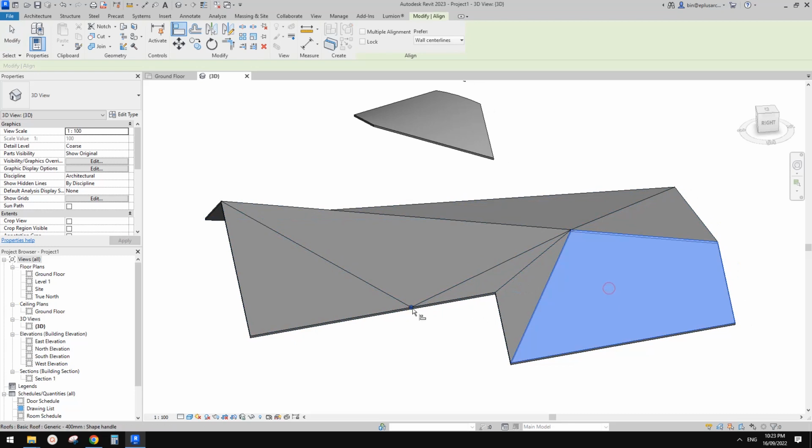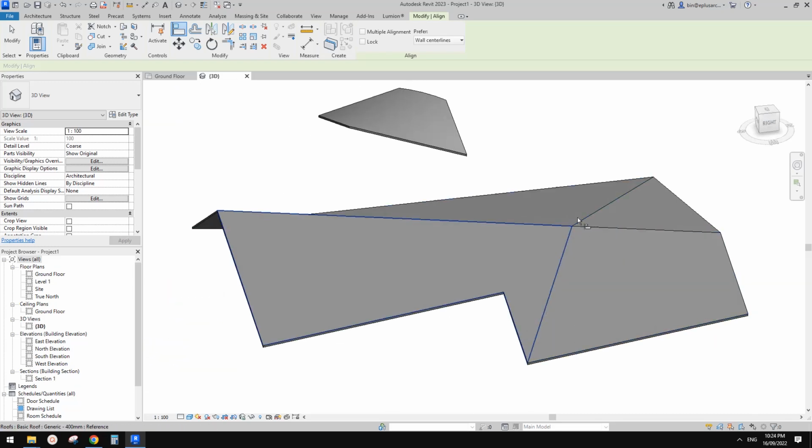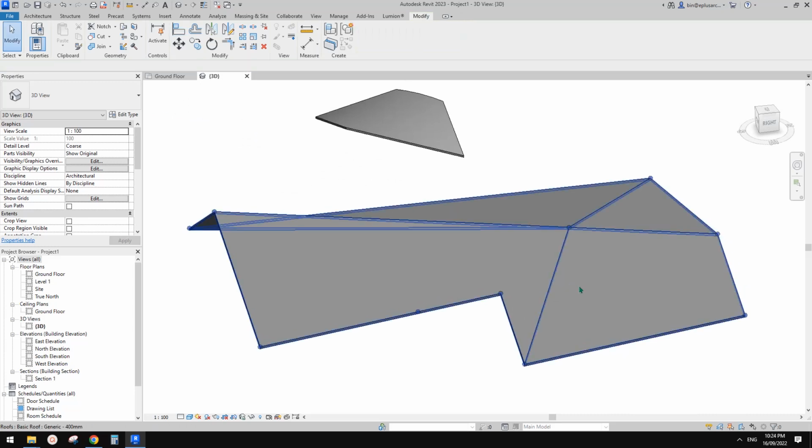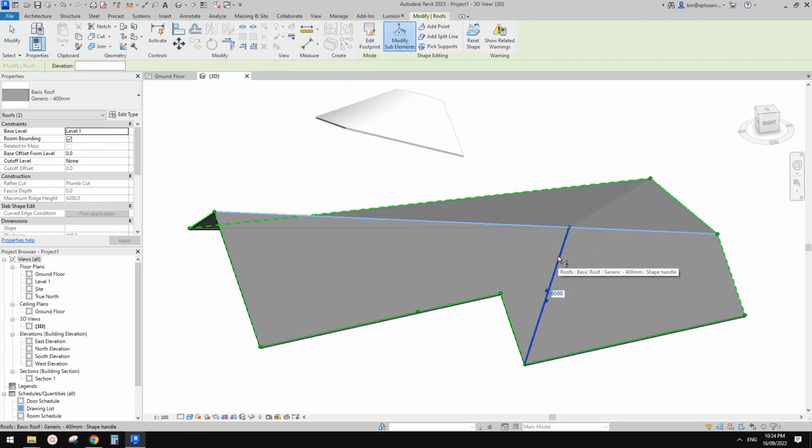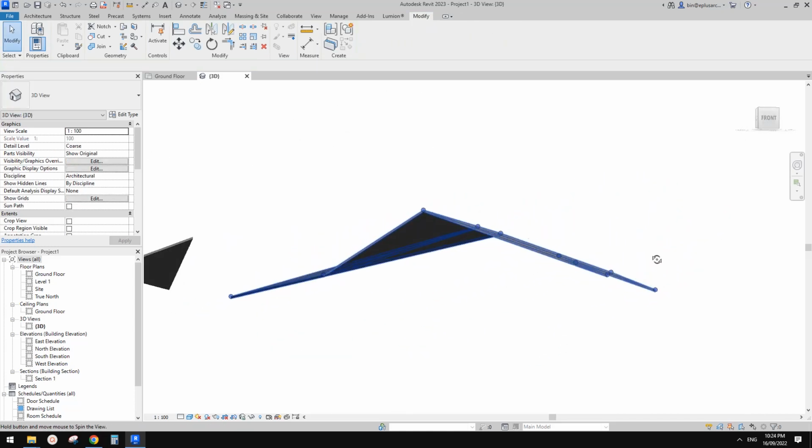Use this surface and do align multiple times, and you will see eventually you will be able to get rid of these lines, and this one as well. Let's just do more. Okay, and now I think we can just get rid of this split line. I'm pretty sure this surface is flat enough. So let's try. Delete. Yeah, great. Now you can see that's one surface.